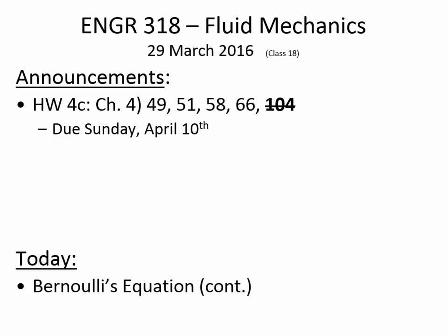Okay, elevation and pressure, but then again, Euler's equation also had that, because inside the term it was pressure plus gamma z in Euler's equation. And so, yeah? Okay, so I'm glad that you're remembering the limitations that it applies. So the limitations for Bernoulli's equation was an inviscid fluid, meaning one that has no viscosity, which is incompressible, and then we apply it for steady flow along a streamline.